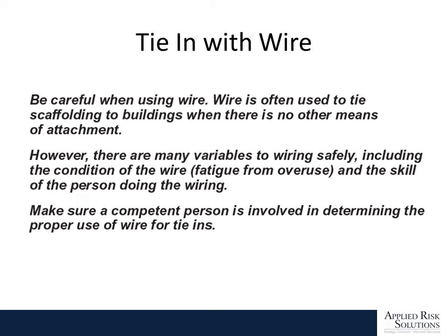Often wire is the only method you've got for tying something in. There are a lot of variables when you're wiring in, using wires to secure your scaffolding. You've got to make sure that the wire is good and that it's been inspected by a competent person.